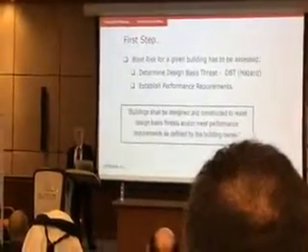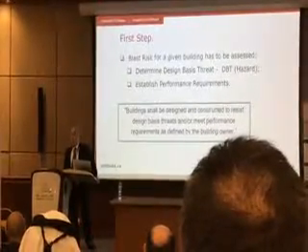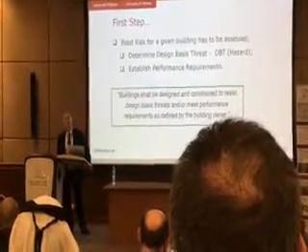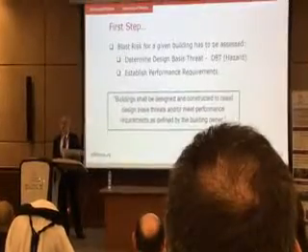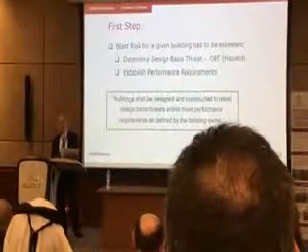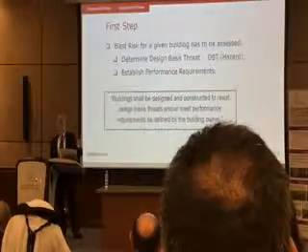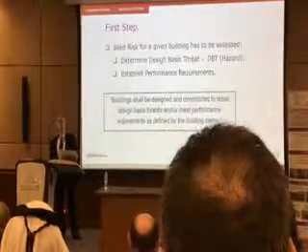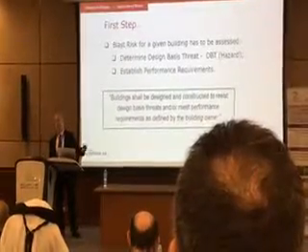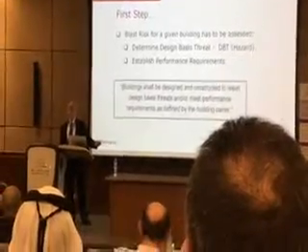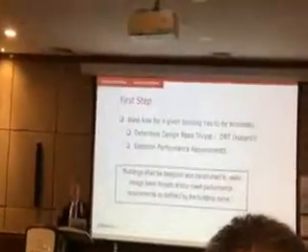How much do they want to protect us, right? After all, it's an embassy, it's important, but it's not very, very important. So they may choose a high level of protection, a medium level, or a low level of protection. Once they give that to you, as a structural engineer, you can't decide for them. The building owner has to tell you the level of protection. Security professionals will give you a threat. With those two pieces of data, then you go and start crunching numbers, okay?